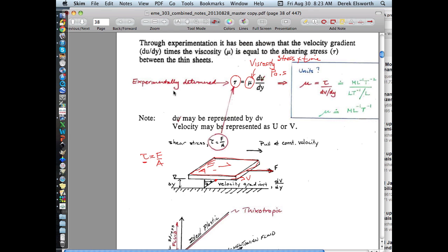But the fluids next to it, it drags only a little bit as fast, because the other boundary condition is that this static bottom here isn't moving. So you have two boundary conditions. The bottom doesn't move, so there's zero velocity here. The top moves, and so there's a velocity v.